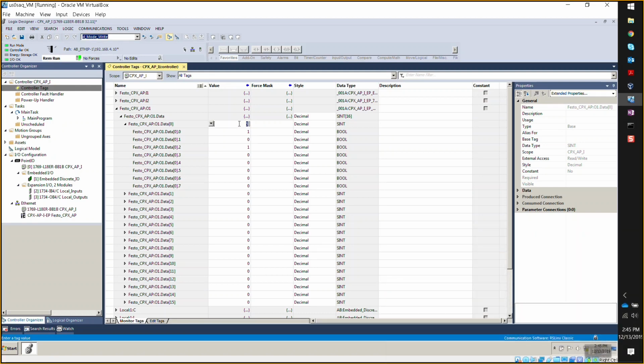Yeah. Now, in this mode, what kind of other module do you have to add? I can add another valve manifold, or I could also add a 4 digital input, 4 digital output module. Okay. Would you like to add the 4DI, 4DO? I can do that, yeah. Okay. All right, let me just grab the cables. Okay, so first I'm going to plug in power. Turn the power off first. Okay, turn the power off of the PLC. Yep. Okay.